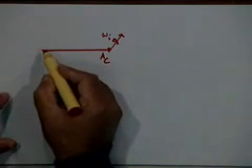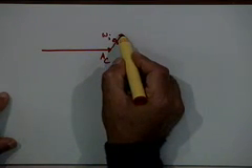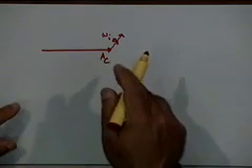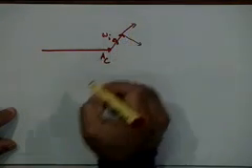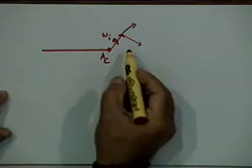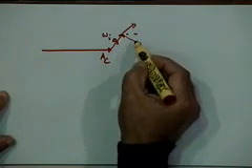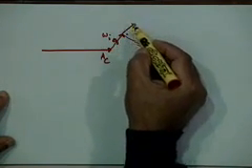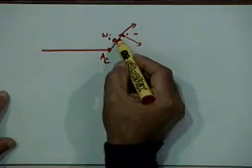And now at this point you are superimposing the two side bands, right, which will look like this, because with respect to the carrier they still have the same configuration, right? They are omega mt and minus omega mt, and they will form an angle of plus omega mt and minus omega mt with respect to the carrier, not with respect to this.